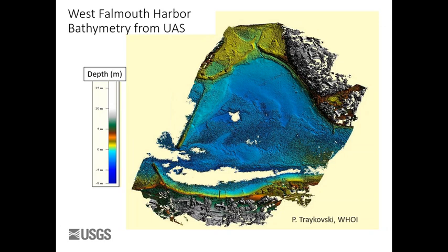How high is the drone flying, like, for instance, in that image you just showed us? So in that last image, I think we ended up with 50 meters. We experimented quite a bit on the vertical, but it depends on how much detail you want, because the closer you get, the smaller your footprint is on the ground, and the more detail you get per pixel. But I think that was about 50 meters.